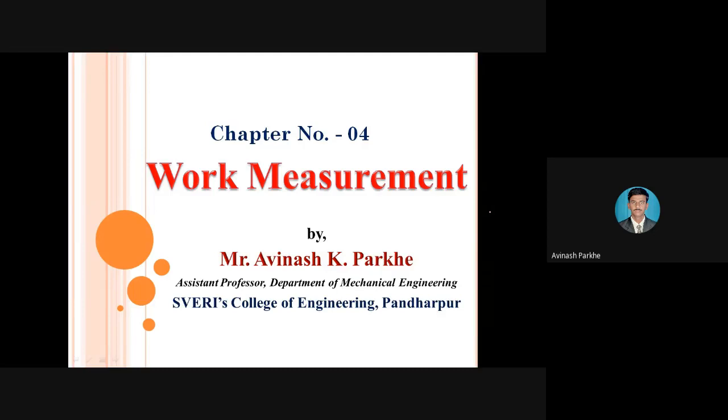Method study means we have to eliminate the unnecessary operations. If I have to convert my raw material into finished goods, I perform a number of operations. If I take the example of the lathe machine, initially I am performing the turning operation, then facing operation, then as per my requirement, I reduce the diameter, that means again I perform the turning operation. Then I perform chamfering, grooving, threading and taper operations. Like that, so many operations we perform on the product, and finally we convert the raw material into finished goods.